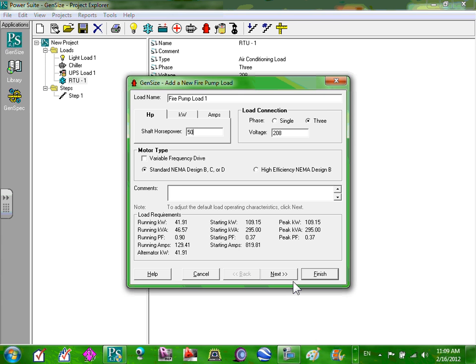You got to be careful, because they want them to be supplied with load, and the breakers that they put on, you know, they're really goofy on how they size them. They want them to burn up. Protection is there as a disconnect, but because it's an extreme fire situation, they don't want any chance of that breaker tripping.